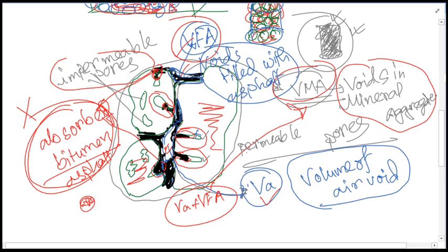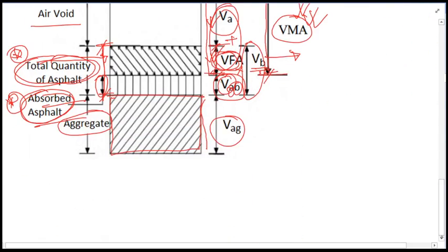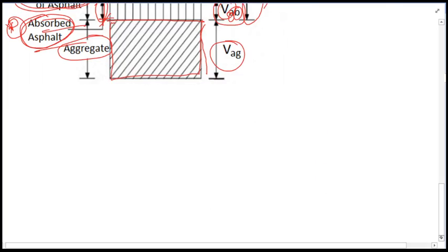Still then there will be remaining portions as well, as you can see. But if we use water in these aggregates, then the water will be able to penetrate through this, and it will be going through the farthest portion of these pores, although the impermeable pores will still be impermeable for bitumen and water, whatever we use. Impermeable will be impermeable in all cases.